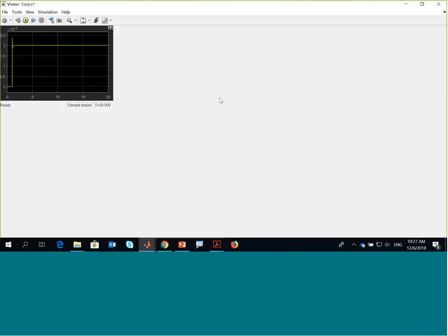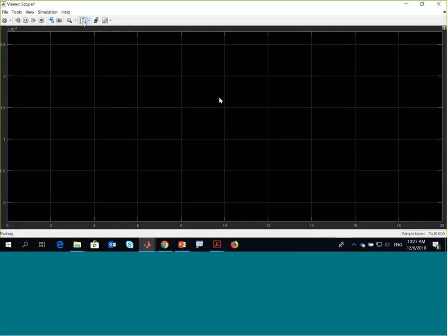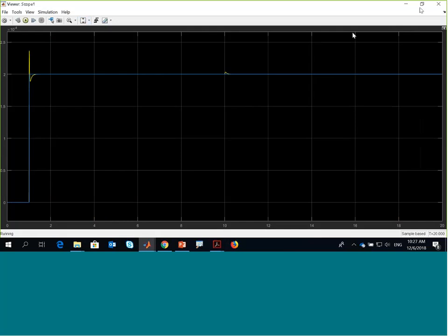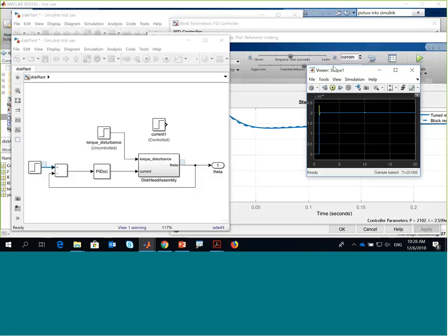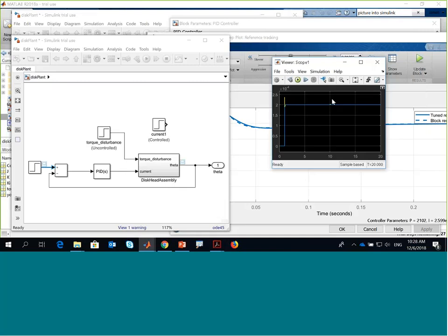So basically, by putting the PID in the control loop, we are adjusting the step response at the initial to be good. The blue one is the step response, the yellow one is the output theta. It overshoots a little bit, and then the disturbance comes in there. It doesn't oscillate like crazy. Very powerful. For those of you who play with controls, you will know what I mean. You will appreciate it, because last time I did manual tuning before, it takes a very long time.